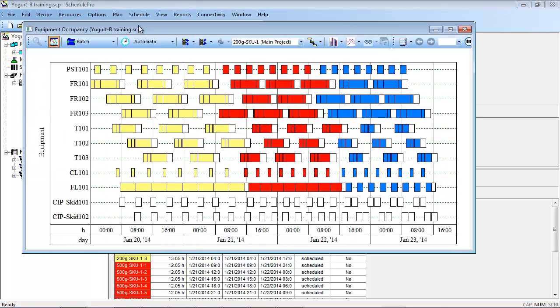The chart shown here is identical to the chart produced for Case A. The only difference is that in this representation we have used a single recipe, and we have introduced the production variances through SKUs linked with this common recipe. This is possible because at scheduling time, the recipe is transformed to serve the specific needs of each SKU which is produced through that recipe. In this case, this transformation involved the use of SKU-specific filling rates and the addition of SKU-producing streams that did not exist in the original recipe.